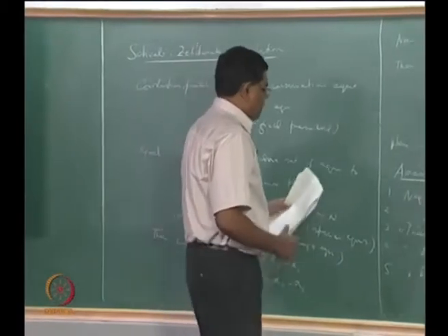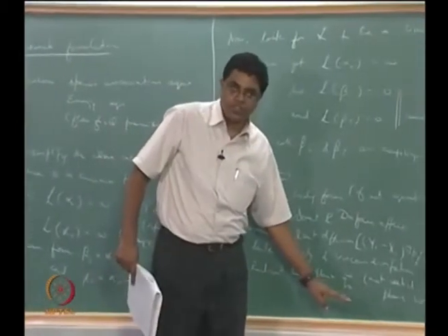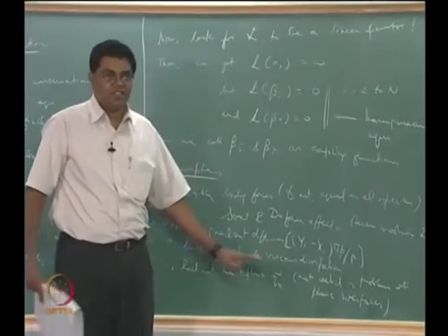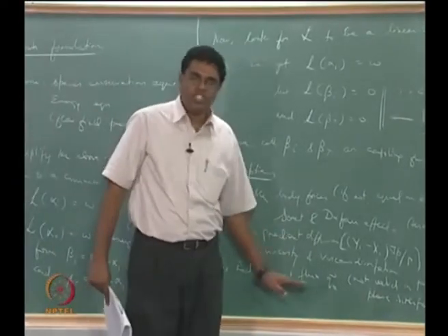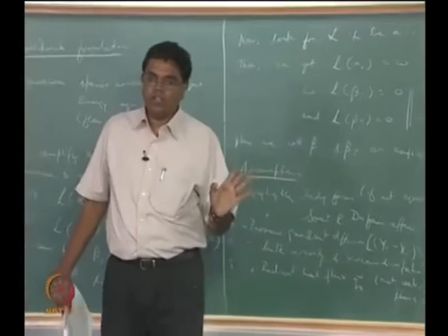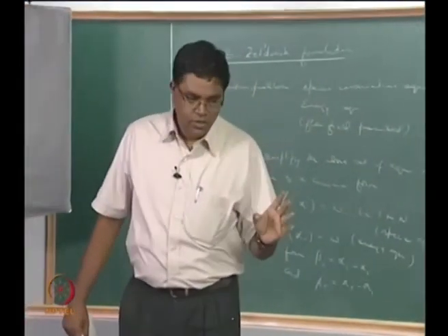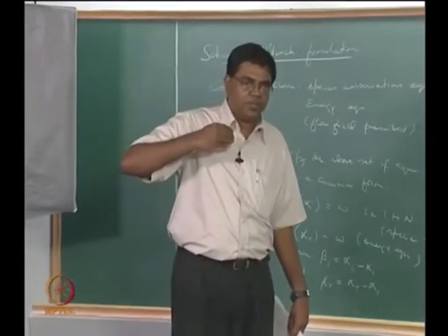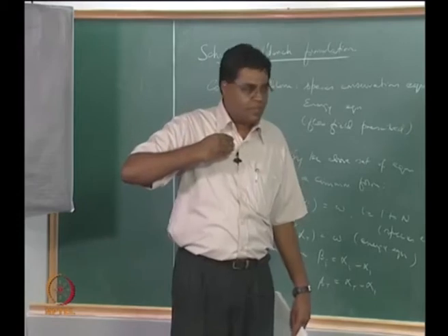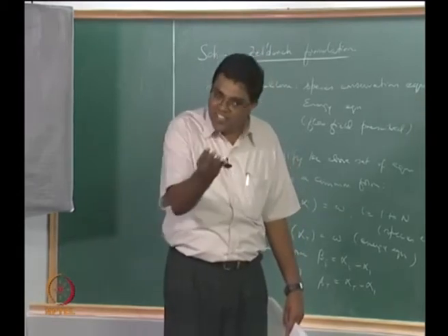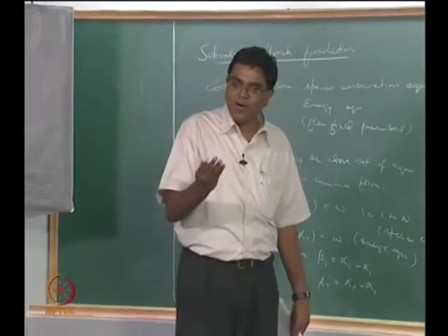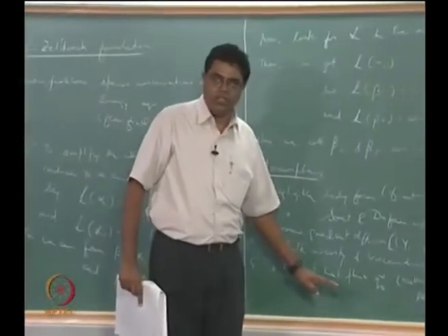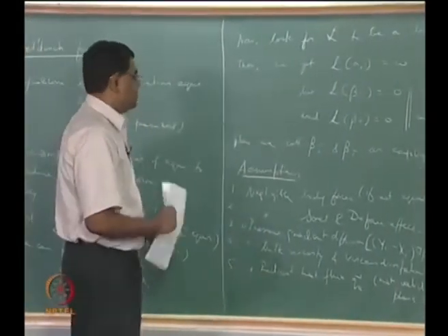Well, of course you will find in the literature there are lots of problems with phase interfaces that have been solved after neglecting radiant heat flux, and you still get good results. It's not terribly bad, okay. But in general the radiant heat flux is significantly small. Now look at a flame: the fact that you are able to see the flame is because you have radiation coming and hitting your eye, and you are like, wait a minute, I could see the flame only because of radiation. How could I not take that into account? The answer is that it's quite small in magnitude, so you don't have to worry too much about this.